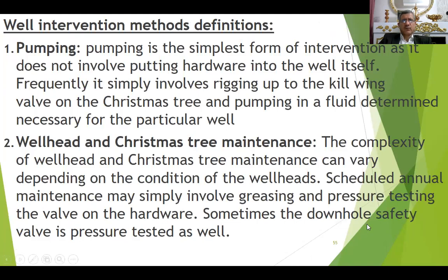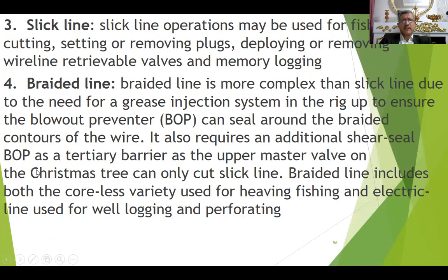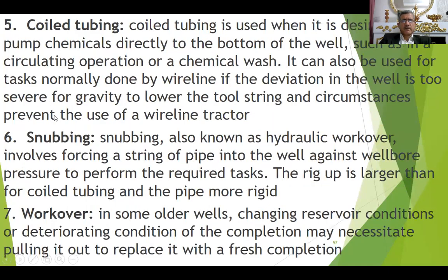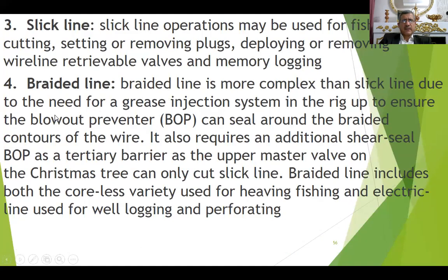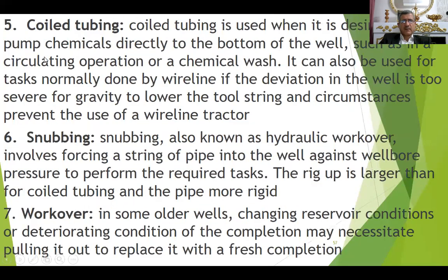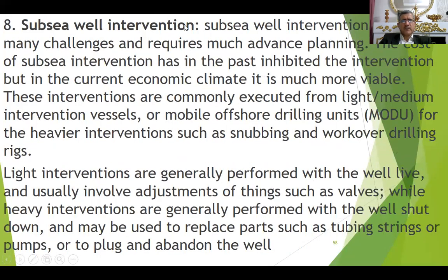Here, if we go into detail, we can see that the intervention methods are 9 types, and we have the definition of each one. We can start with pumping, wellhead maintenance, and the Christmas tree, slick line, braided line. We have electric line also included with this one, with the braided line. It is very similar. Coiled tubing, snubbing, workover, subsea well intervention.